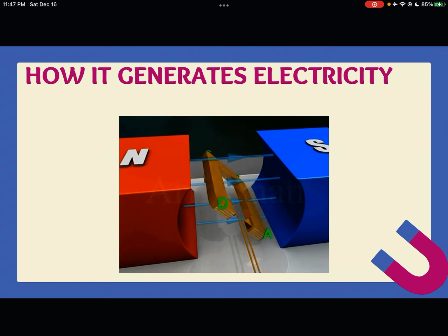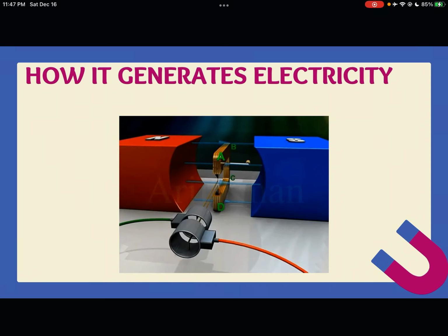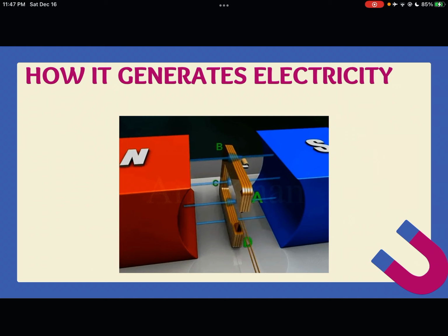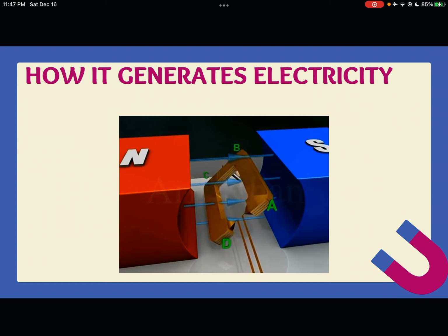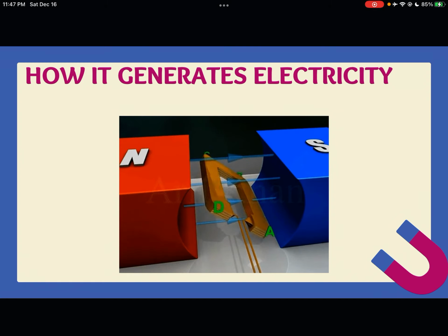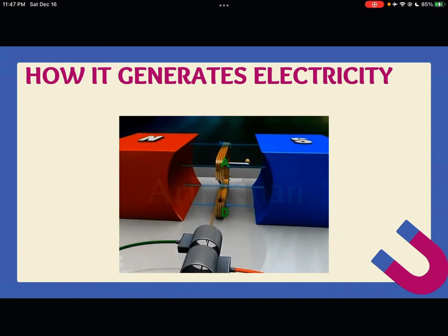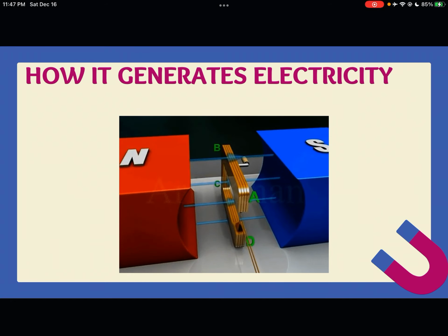But due to the fact that the armature is spinning, if you spin your right hand rule with it, you would see that the circuit that's currently carrying the out will suddenly carry it in, and the other side does the same thing. If it's out, it's in. So it's in, out, in, out, in. This is the reason why it's called an AC generator, alternating current. The current alternates. Sometimes it's in, sometimes it's out, depending on where the armature is between the magnets.